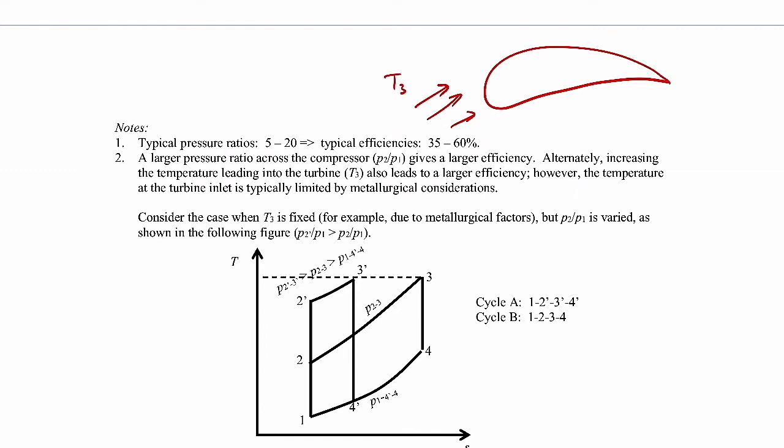It's very hot. So one of the design features that they actually implement in most turbine blades is they'll have these little injection ports on the blade at strategic locations. And these are connected to some of the incoming air coming into the engine. So they bleed off some of that air coming into the compressor, and it's at a relatively cold temperature. Then they feed it into the turbine blades through the base of the turbine blade, and it comes out of the blade.